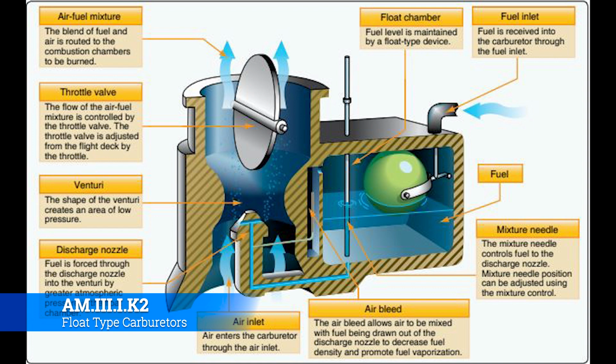So if there's a lot of fuel being consumed, then that's going to drop the bowl level, which then drops the float, which takes in more fuel. If it's just idling, it's not taking a whole lot, the bowl will generally stay pretty full, and that'll keep the fuel from flooding the engine and causing all kinds of problems. Now, the way that it does that is through the float itself, which isn't labeled here, but it's a little green ball that just floats up and down. It's pretty simple, pretty straightforward.